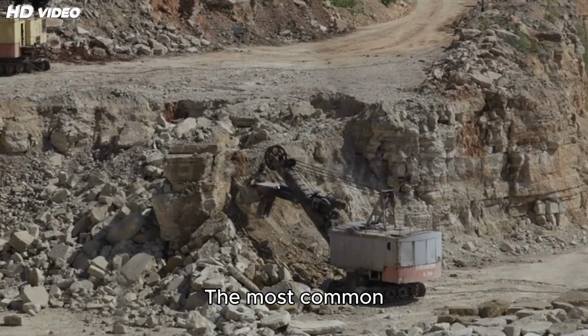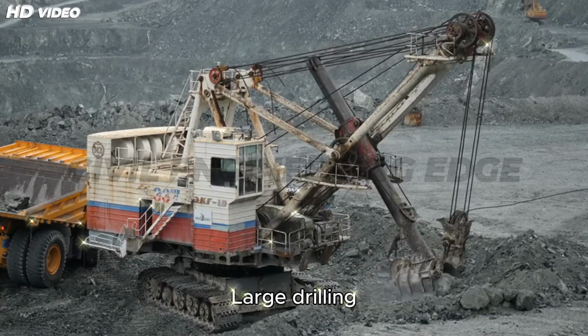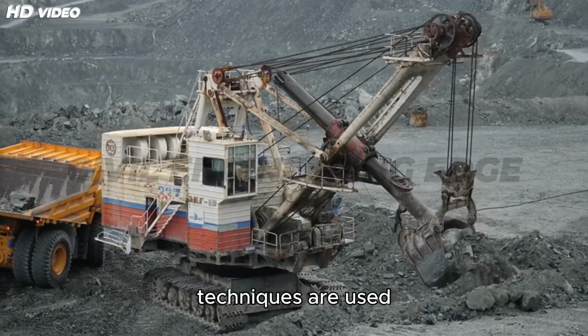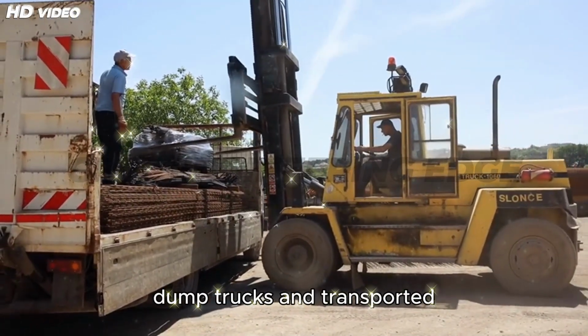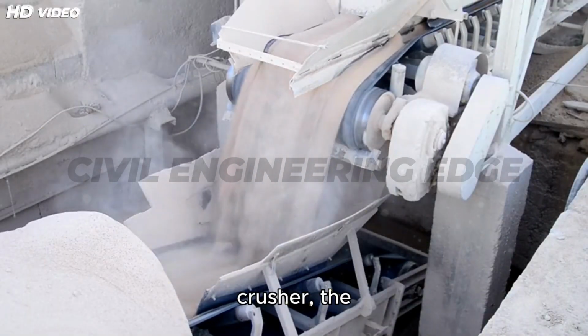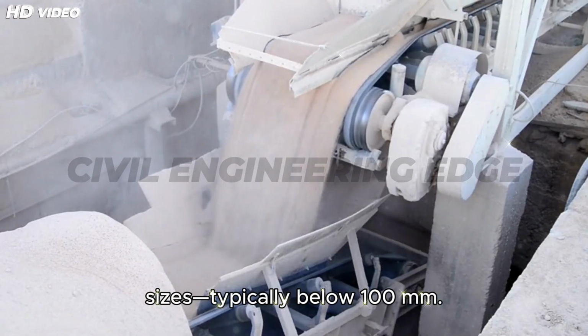The most common mining method is open-pit quarrying. Large drilling machines, excavators, and blasting techniques are used to loosen massive rocks. These are then loaded into dump trucks and transported to the crushing plant. At the primary crusher, the materials are reduced to manageable sizes, typically below 100 millimeters.